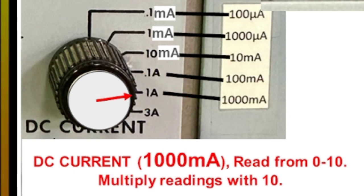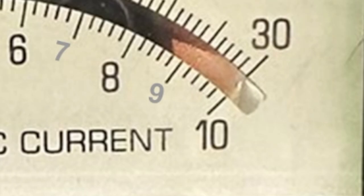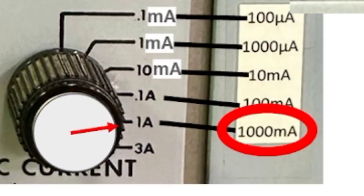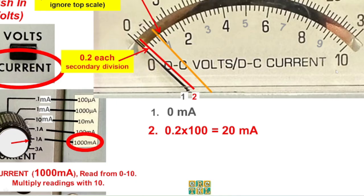Now let's move on with the same current meter, still on the 1 ampere selection, but this time we will be thinking about 1000 milliamperes as our limit. This time, this is 10 only, and to make it 1000, we have to multiply by 100. And so, we will be getting answers multiplied with 100. Instead of 0.2, we will be getting 20 milliamperes. The 0.9 multiplied with 100 will be 90 milliamperes. And so on with the others.